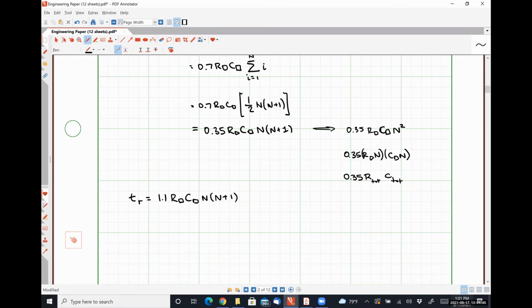But there's a secondary delay that we need to keep in mind as well. For an N-well resistor, it's practically never going to matter. But once we start talking about propagating signals down metal runs and stuff like that, this is a really, really big deal, okay? So I want to define the intrinsic delay.